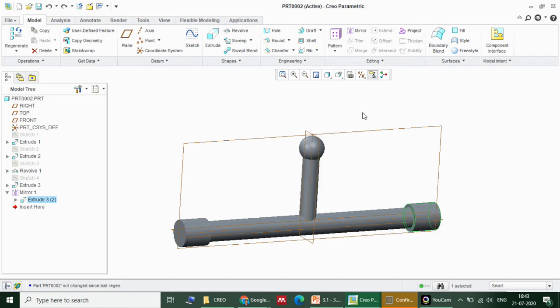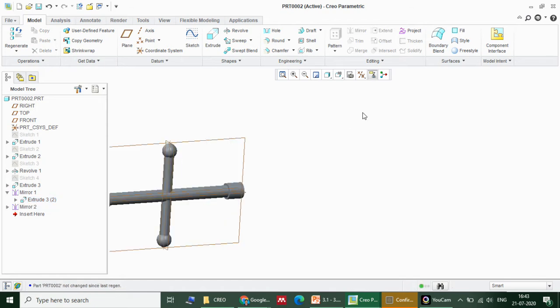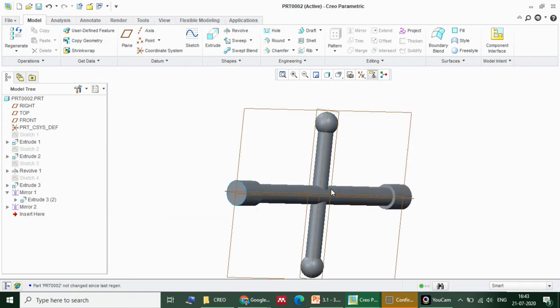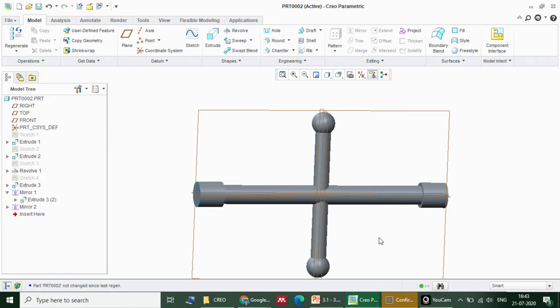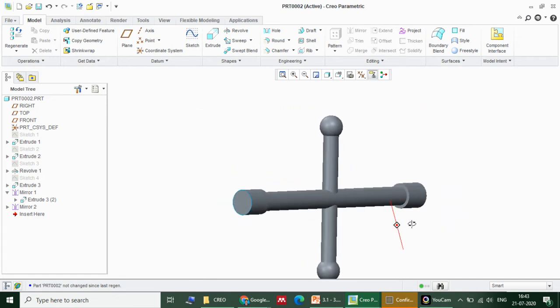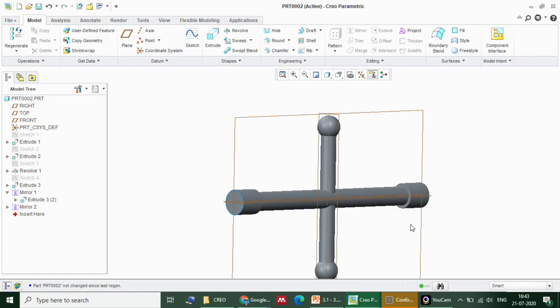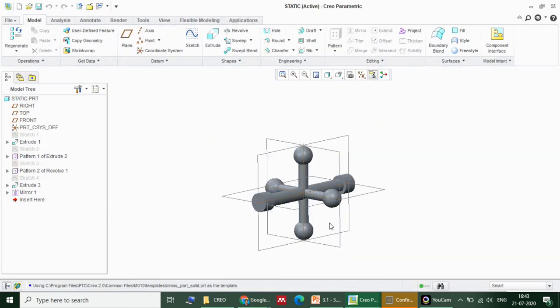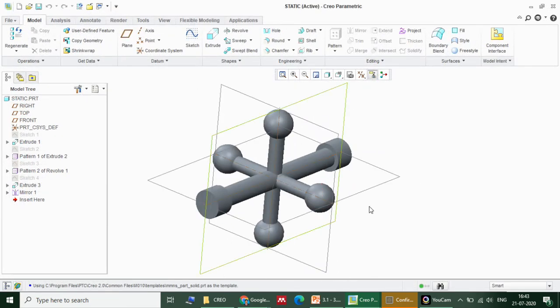Now the solution is to add another mass opposite to it. Now what will happen? Another disturbing force which is exactly equal in magnitude but opposite in direction to your previous force will start and exactly balance out the disturbing force. Now this is one way to balance. So that's a very simple case study, right? Now let us take this example. What is the difference between static balancing and dynamic balancing?